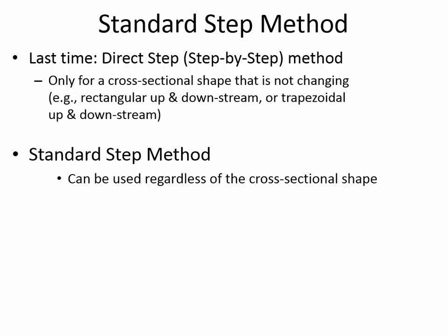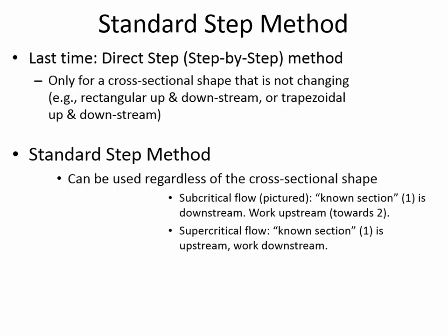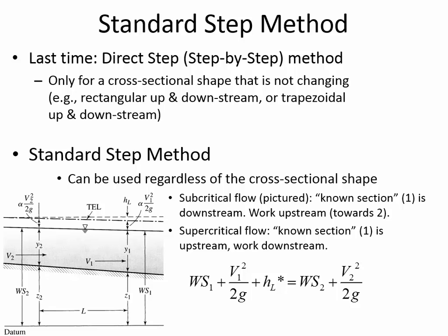And so the numerical model that's used by the Army Corps of Engineers and a lot of private contractors is called HEC-RAS. And in fact, this semester in senior design, the students in the hydraulics and hydrology group are using HEC-RAS. And behind that is this method that you can set up with a spreadsheet. You don't have to do it in a computer model in a fancy graphical interface. You can just set it up in Excel, and that's what we'll do today. So let's take a look.